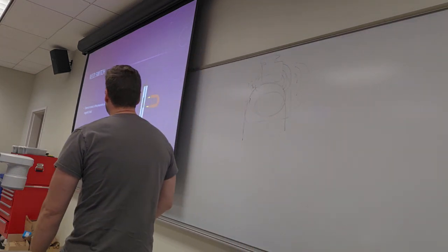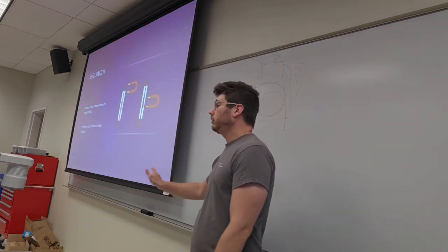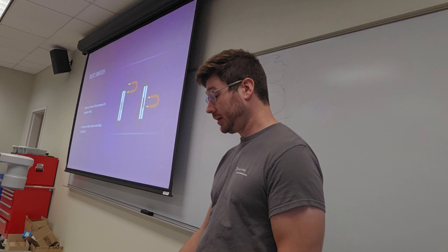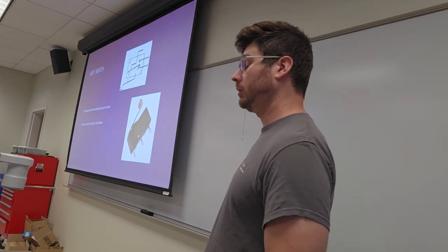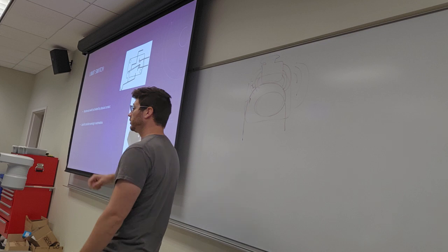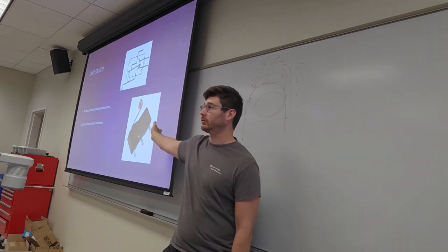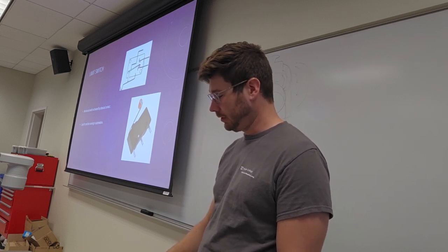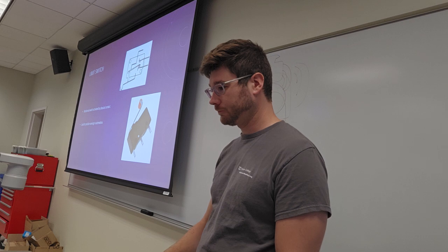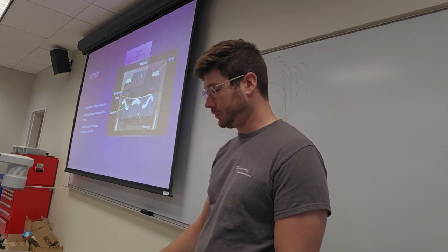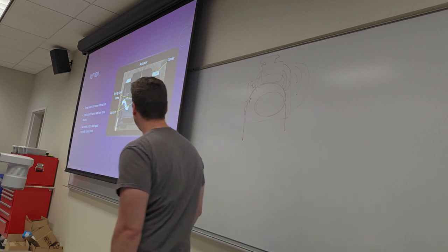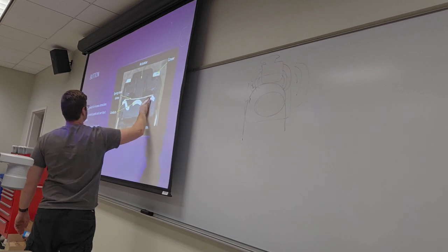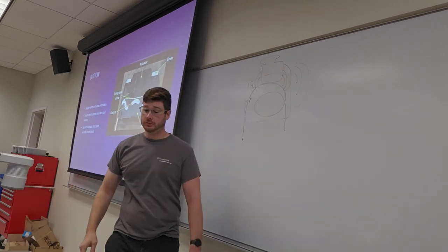All right, so again, preview. I would love it if you turn these into flashcards or something for yourselves. Make sure you know these terms. They're not complex by any means, but knowing what a reed switch is, knowing what a limit switch is, knowing this by sight, right? If I show you this, you say that's a limit switch, or that's a... what do they call it? Limit switch, or... I'm blanking. I'm sorry. Then this is knowing how a button works, right? That we're bridging metal, or just deflecting this piece of metal that is bridging these two contacts, or this contact and these contacts.